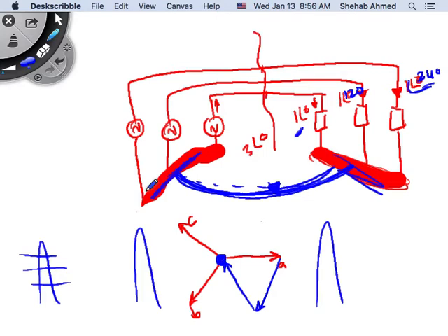The same, right? If you have two nodes that are connected but no current is flowing, it means current only flows if there's a voltage difference between nodes, right? So if neutral current is flowing, what does it mean? It means that I have a difference in voltage between this node and this node, right? So if there's a difference in voltage between these two nodes, then the neutral point of this three-phase system and the neutral point of this three-phase system are not at the same voltage level.